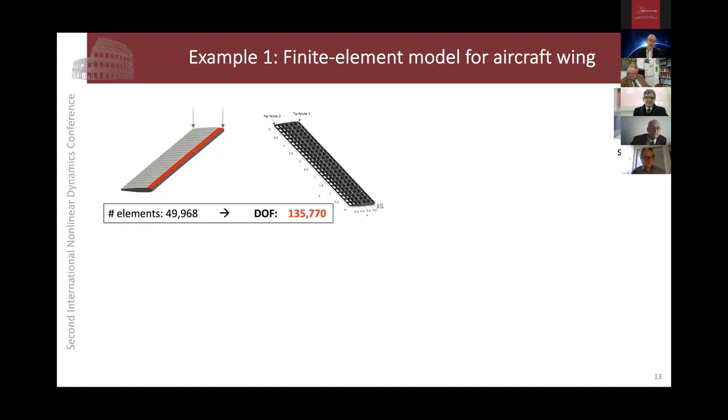This is now a 270,000 dimensional phase space, okay? So instead of experimenting with projections, this code computes these invariant manifolds exactly, and reduces the dynamics to them. And if there's no resonance, that invariant manifold is two-dimensional. On that one, without any simulation, you can find the force response as an appropriate fixed point, because you can factor out the rotational degree of freedom in all these problems when you use polar coordinates in normal forms.